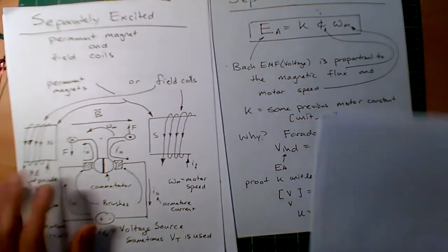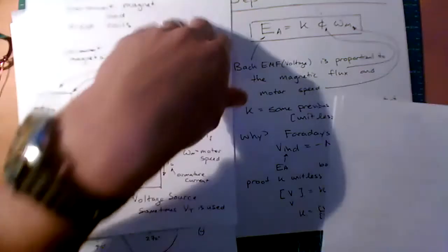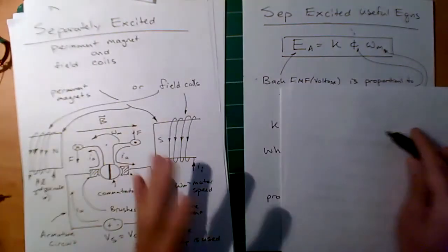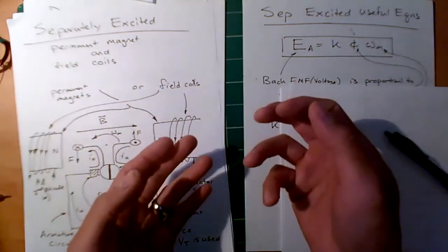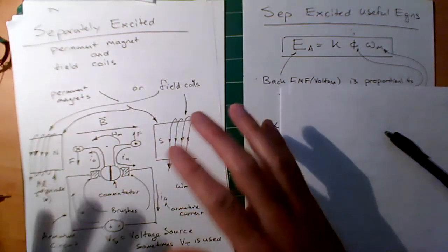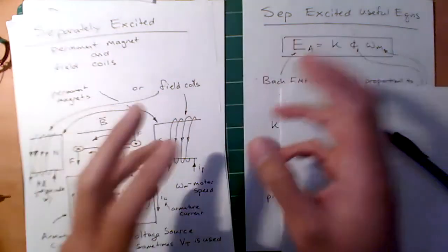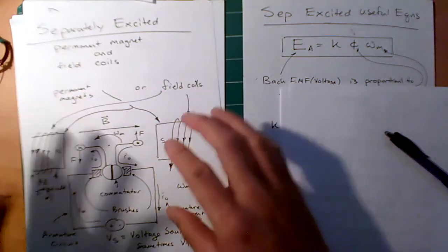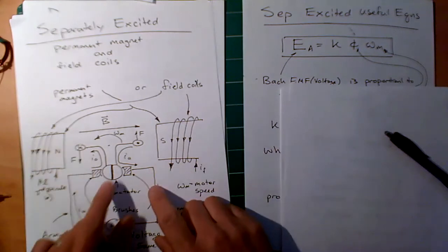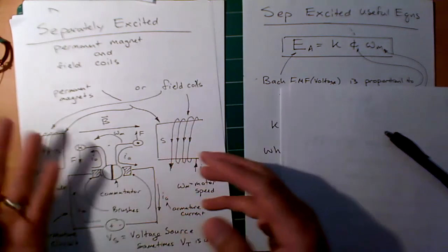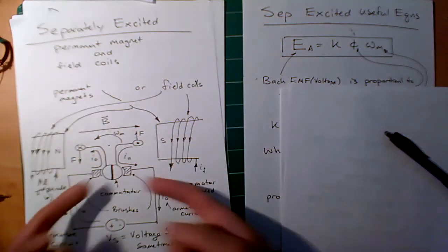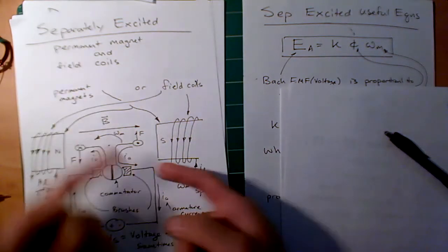Okay. I know this was a heavy lecture. I know there was a lot of material on this, but I hope this gives us some perspective on the AC voltage that's generated in a DC generator when there's no commutator, and how it's rectified with the commutator, and how the internal mechanics of a DC brushed motor work, right? And why the commutator is so necessary in a DC brush motor, right? It's necessary both for generation and for motion when I apply electrical energy to it.